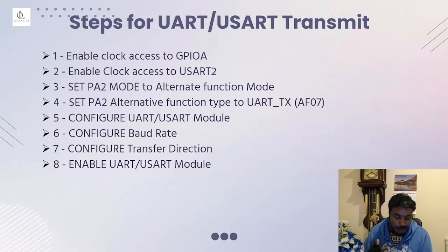So this is what you're going to learn: how the transmit bits are used in terms of this STM32F411 microcontroller. We're using the Nucleo F411RE board. And these are all the steps. First, you got to enable clock access to GPIO.